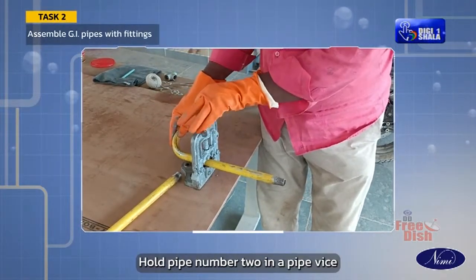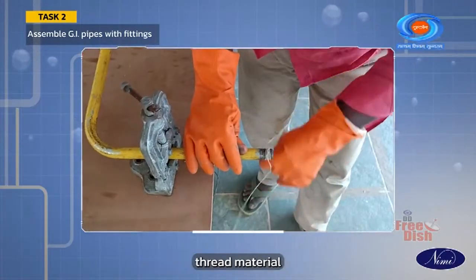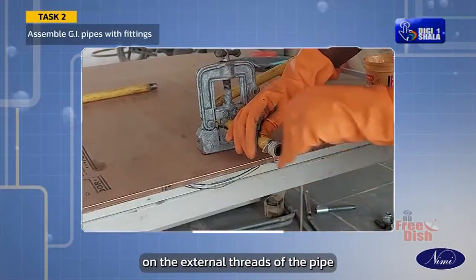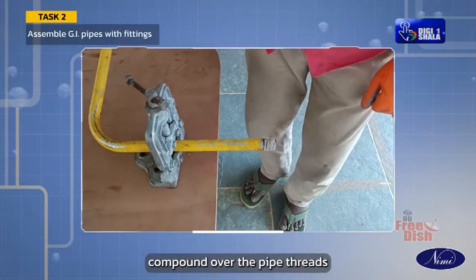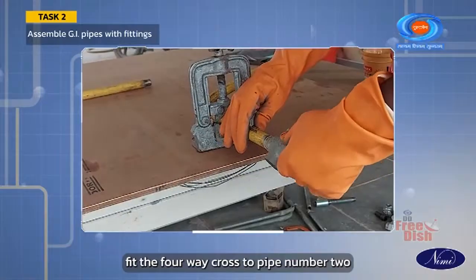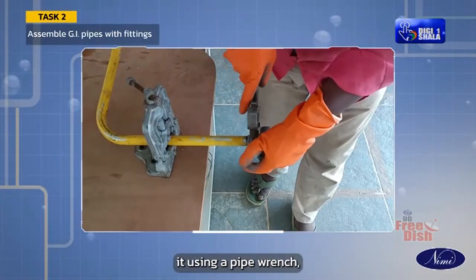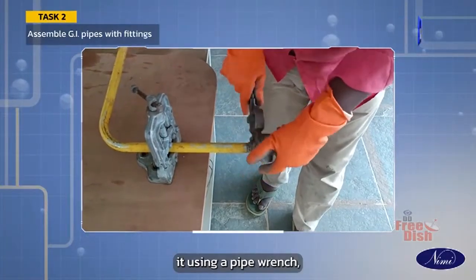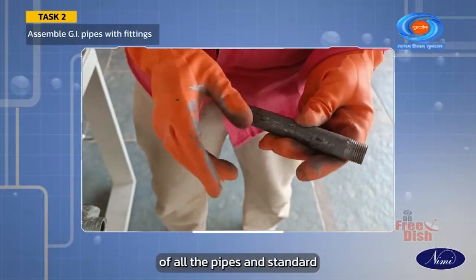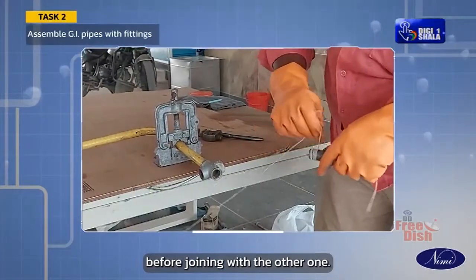Hold pipe number 2 in a pipe vise. Wind the hemp packing or cotton thread material on the external threads of the pipe. Apply sealing compound over the pipe threads. Fit the 4-way cross to pipe number 2 and tighten it using a pipe wrench. Wind the hemp packing to the external threads of all the pipes and standard fittings and apply sealing compound over the threads before joining with the other one.